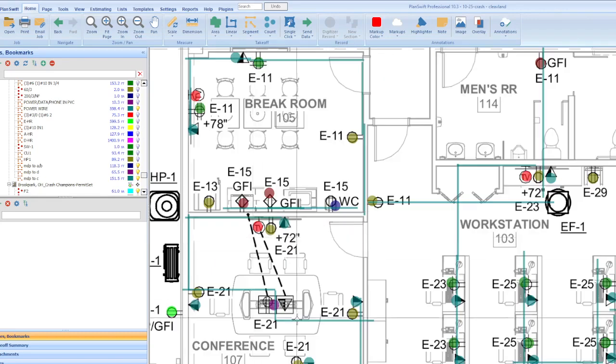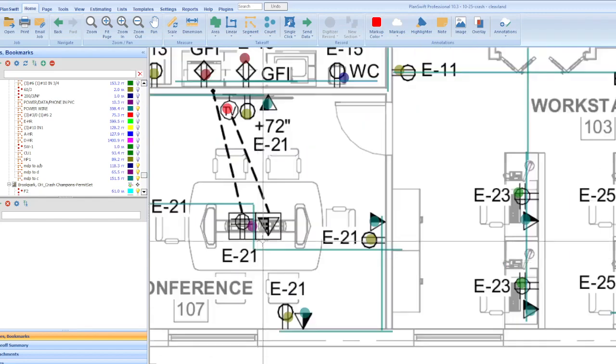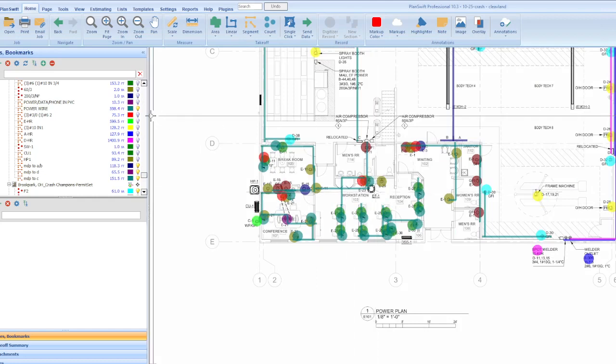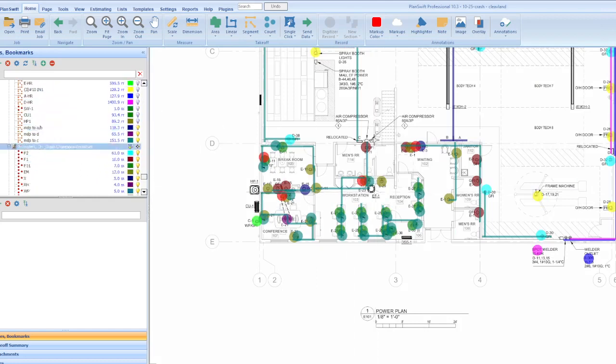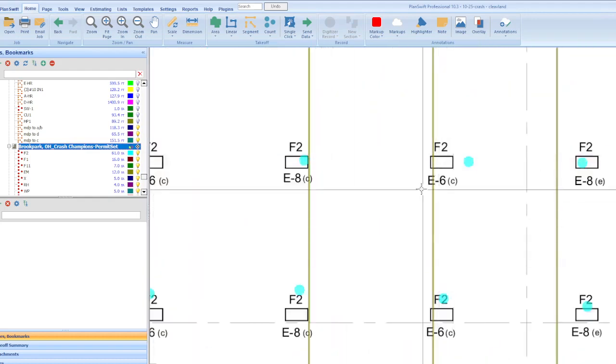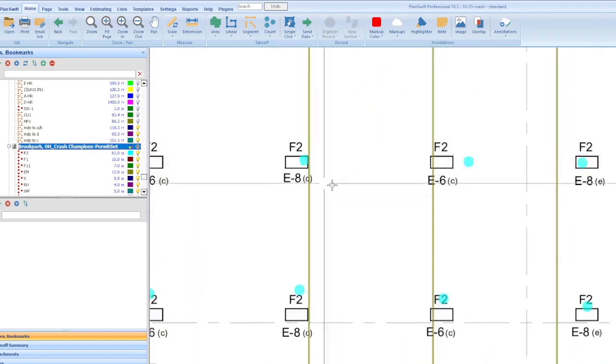We got some underground, so that's going to be PVC, and then we have to transition it up through the new partition. This is a floor box. It shows it on the table, but chances are it's in the floor, where the contacts are anyway. Okay, and so you have to do all of that. Okay, and all your lights. And the same thing with the lights. You know that they're going to